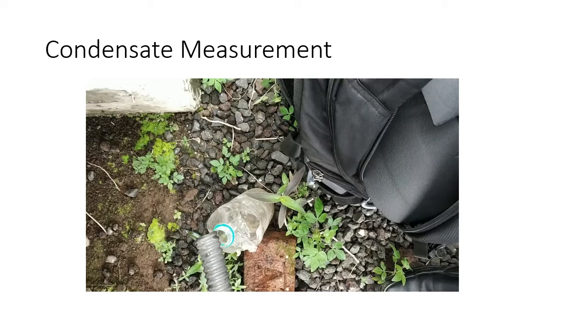In this video, we will see the condensate measurement. This measurement is very important and shows the health of the overall cooling system of the shelter. If your condensate is high, it means your water rejection from the EFC unit is more. That means you have a fresh air leakage inside the shelter, and the maximum capacity of the EFC machine is being utilized in generating the condensate.